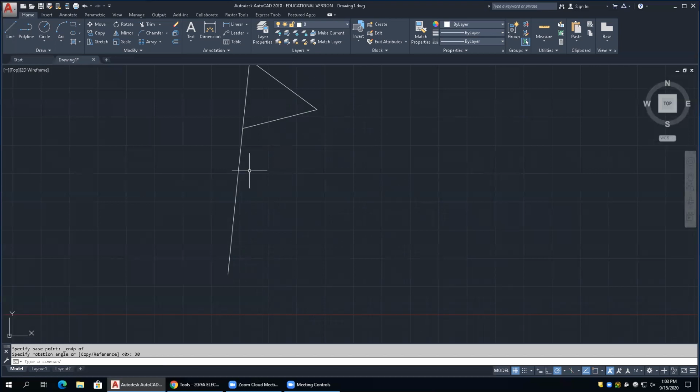If you're going to do that, you better know the exact angle, okay? In my business, mapping, we get into rotation issues sometimes where the guys out in the field have screwed up the angle, and they might have screwed it up by 5 degrees and 30 minutes and 3 seconds. So when I rotate, I have to get that exact. Otherwise, things are not rotating exactly into position. So it's really, really critical when you do rotations: where the base point is, the amount you're rotating it, and whether it's plus or minus.